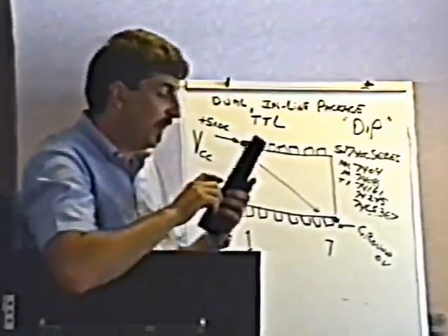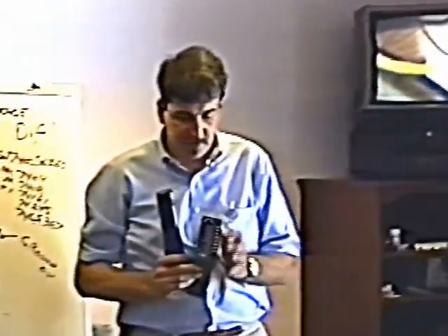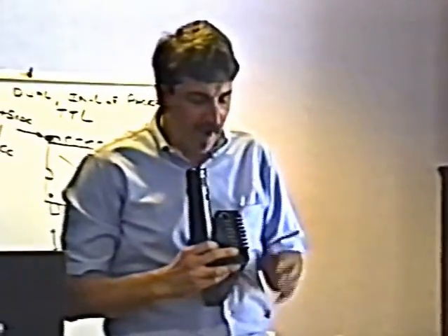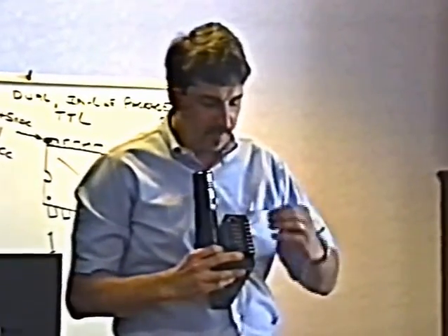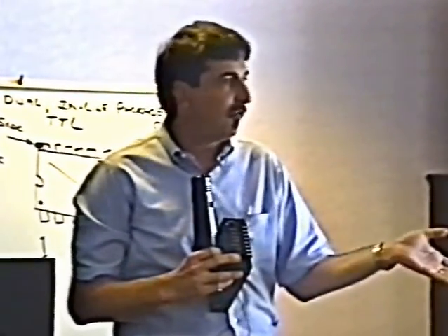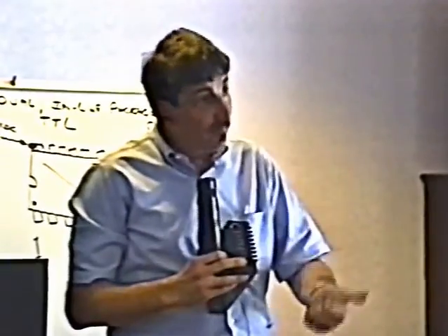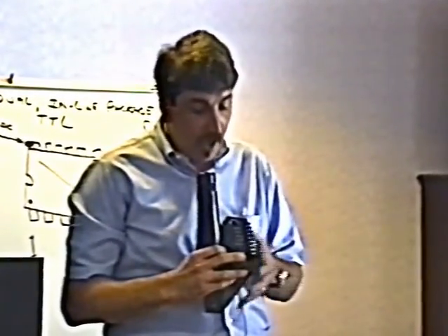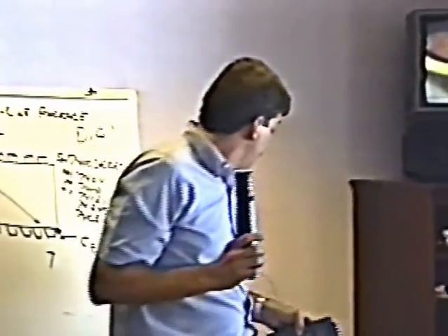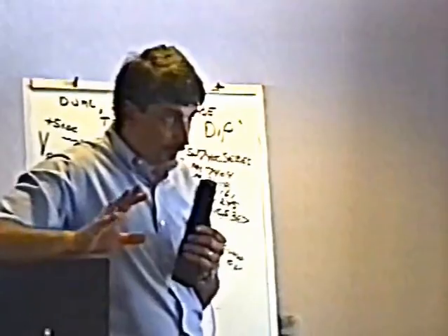And since there are only a few screws on the power supply, you don't even have to mount it. It's not a bad idea to take another power supply, just move all the wires over from one to the other, try the new power supply first. But if everything's okay, your 5 volts is okay, your connector's good, and maybe even you've tried another power supply and you still have the problem that I just showed you, you have a board failure.